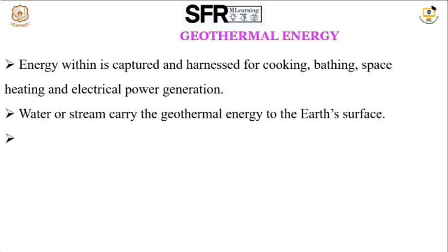This is the working of geothermal power plants. Hot water is pumped from deep underground through a well under high pressure. When the water reaches the surface, the pressure is dropped and causes the water to turn into steam. The steam spins a turbine which is connected to a generator that produces electricity. The steam cools off in a cooling tower and condenses back to water.